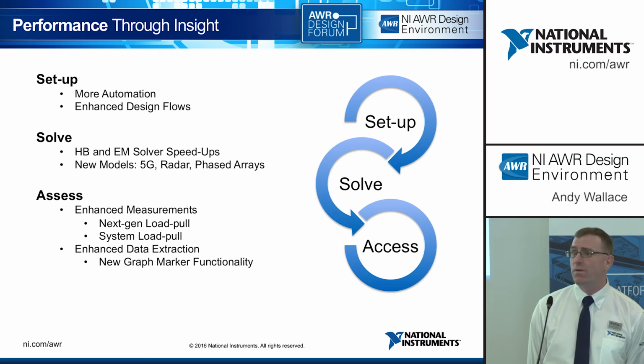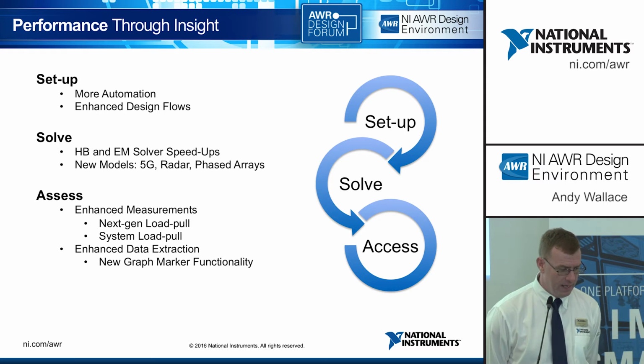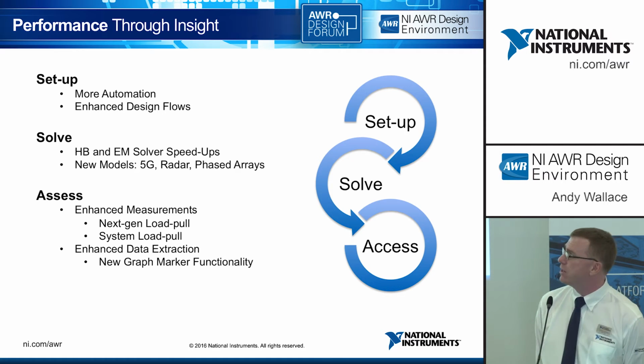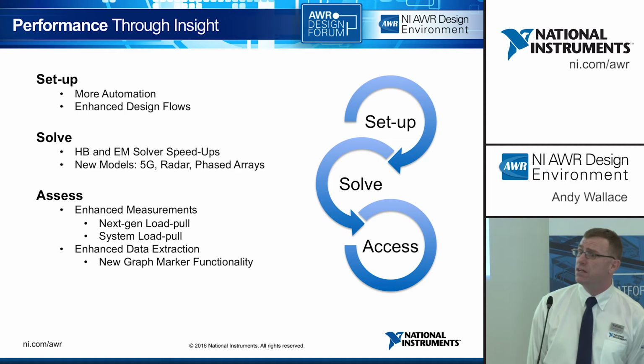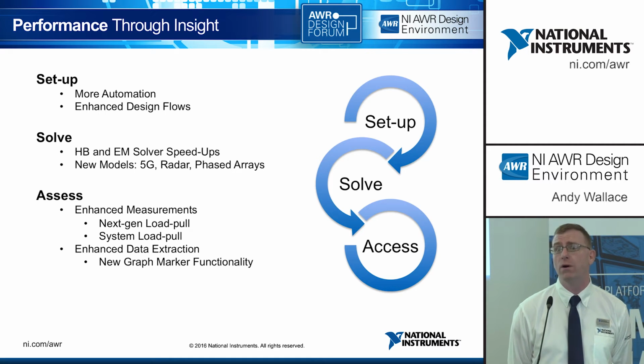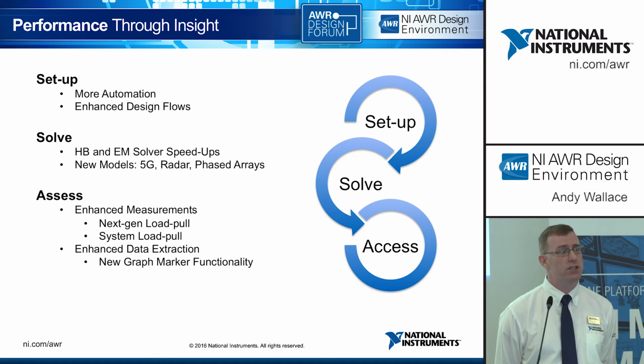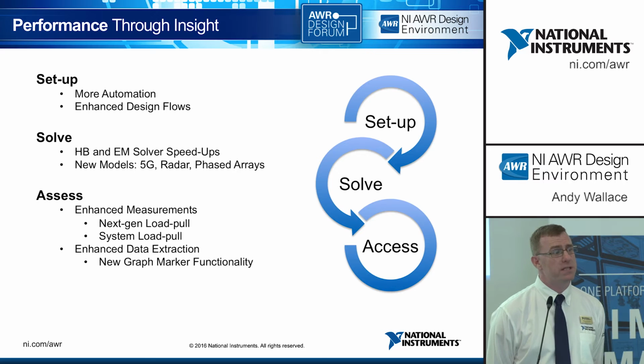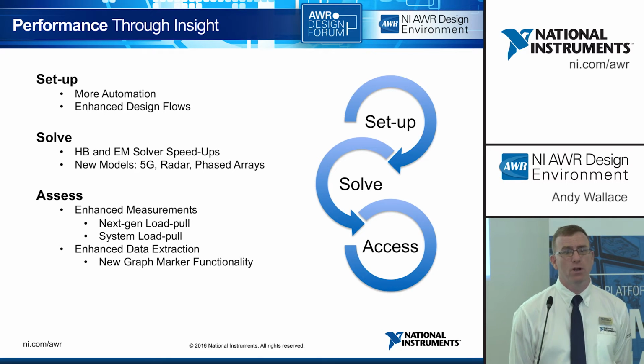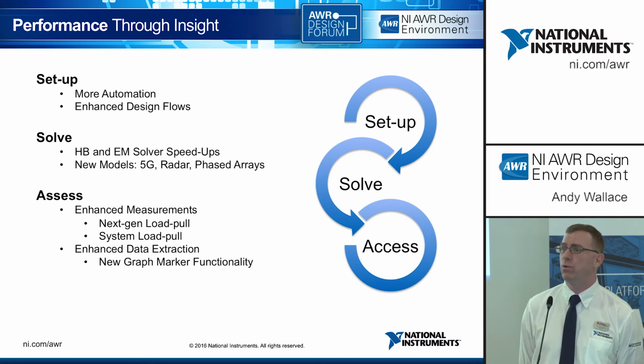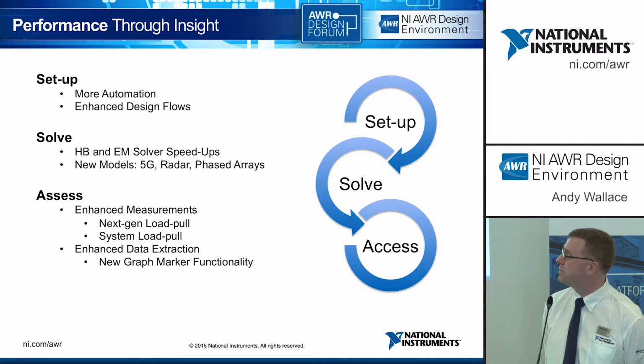And then once we've got that data, how do we improve the access to that data? Next generation LoadPull, and we've taken LoadPull to the systems level as well, where we can look at system simulation, modulation schemes passing through a design, and vary the source and load impedance of the underlying amplifier in that systems level simulation. We can look at effectively contours for EVM or contours for ACPR type measurements.